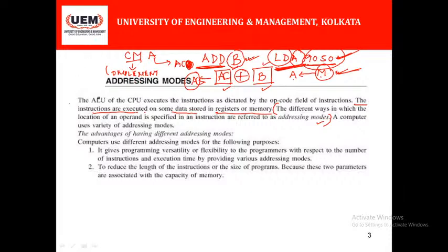So what we do basically in this instruction, look at that, there is no operand field or operand location field such as memory or register, which will store the address of the operand or the operand itself. What this instruction is basically doing, we are complementing the value of the accumulator. So AC bar, we are performing AC bar here, and the result is stored in AC.